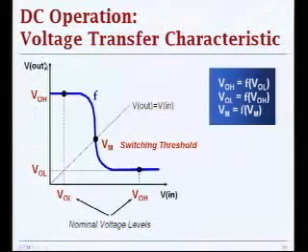So over here we plot the DC transfer characteristic of an inverting gate in this case. We will develop most of our ideas on an inverter example because that's the major building block in digital circuits. And once you understand the inverter, you can understand all the gates. This graph plots the output voltage of an inverting gate for a range of possible input voltages.